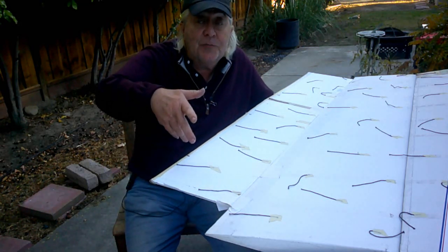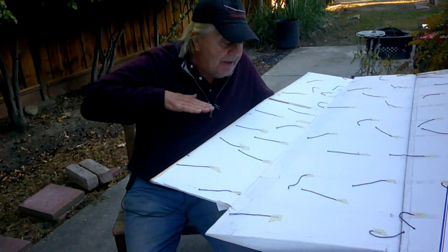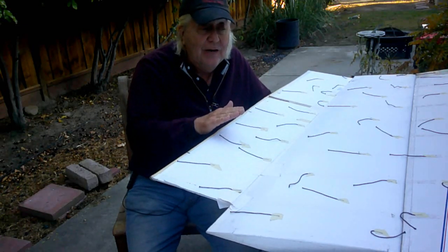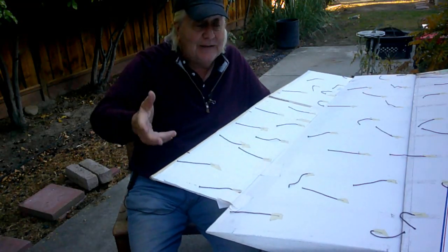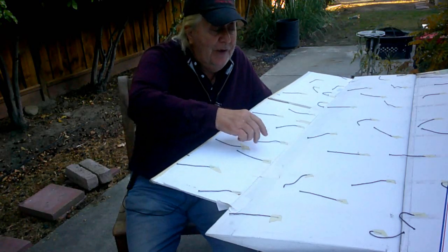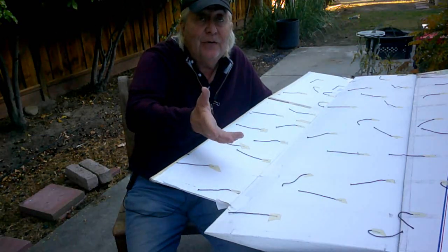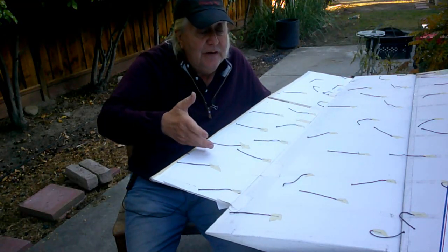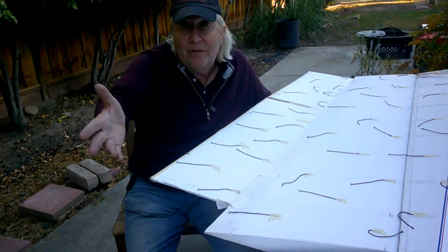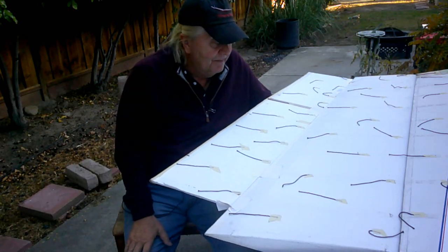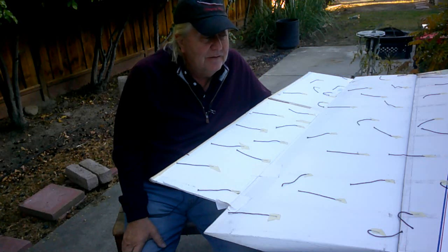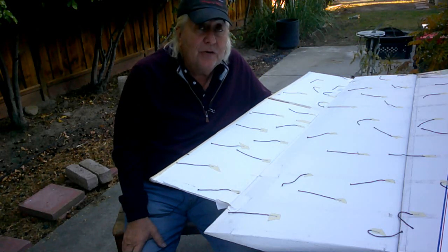We can go back and explain why when I just tacked on elevons on the rear and activated those up and down, the flow looked great on the wing and I had lots of control. And then when I removed this and cut out the elevons, it didn't work as good anymore. It worked a little bit, but doesn't work as good because the Reynolds number's back down to 410,000. So how do you save the design? Well, you need a bigger chord.